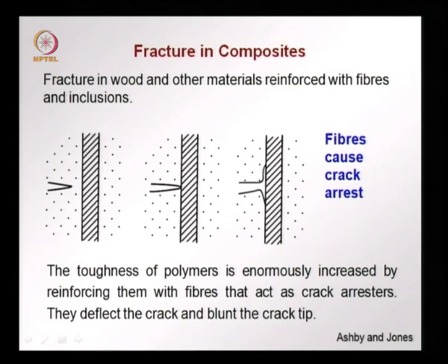So what we see when the stress continues to increase is now the crack envelops the fiber and it does not propagate, does not extend further until the fiber is either broken or it slips and you have significant deformation in this region. So this gives rise to two phenomena that help control the crack. One is the crack is now blunted, instead of a sharp crack we have now a blunt crack tip. So this decreases the stress concentration and therefore you need now more stress to keep the crack propagating.